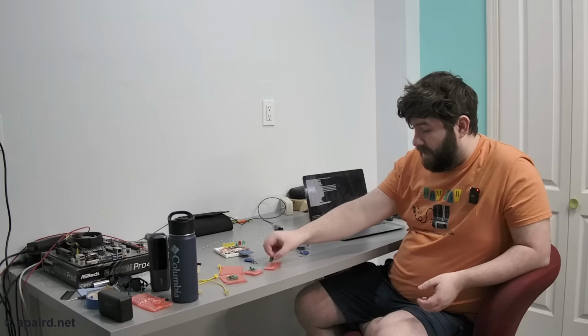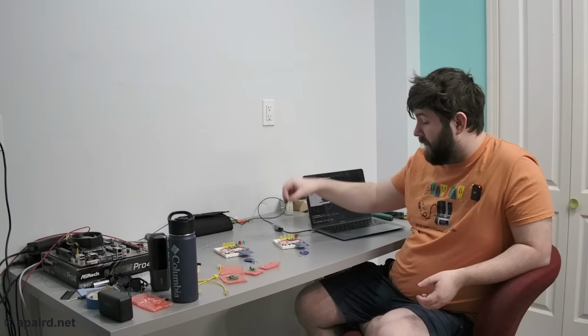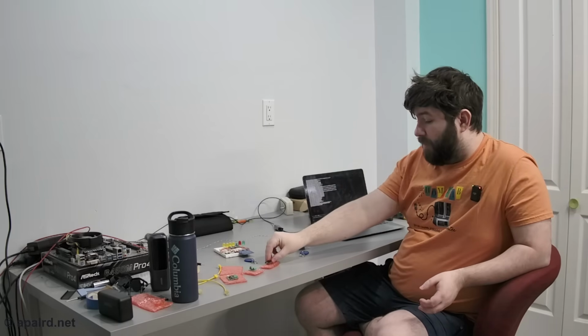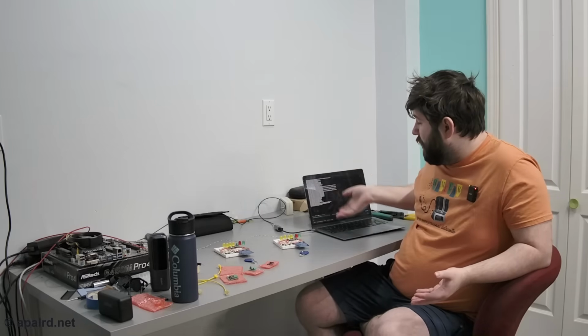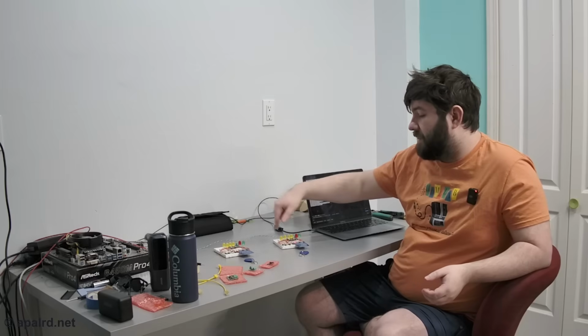So this is mostly a debugging aid for myself. I could plug in the USB serial port to debug it, but I've got a network, so why not? Basically I rerouted the output console from the ESP32 to just send a UDP packet to multicast every time. So as long as my laptop subscribes to that multicast group, I just get a UDP stream full of all of the debug messages. Super handy. I can filter them by who they came from. Each of these guys has a unique link local IP address, so I can just see what IP address it came from. And I've got debugging.